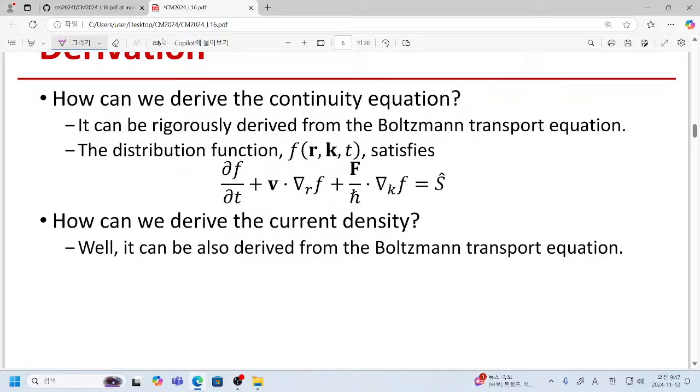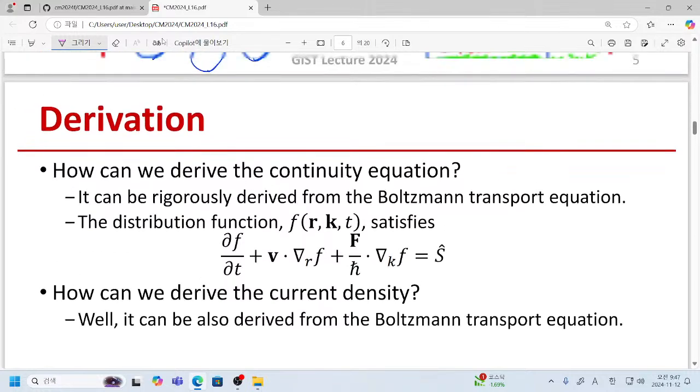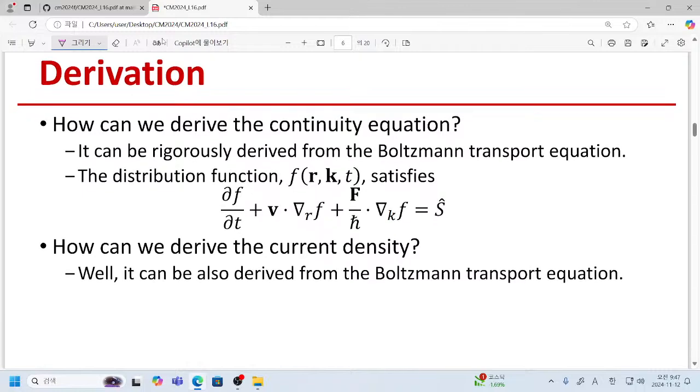There are particles, and these particles are moving. Since they are charged particles, they are pushed or attracted by the electric field, and when they have a temperature or density gradient, then they diffuse. All of our dopants, electrons and holes share the same physical mechanism. That's the reason why we must solve the same problem. However, the techniques are a little bit different because the scale is different.